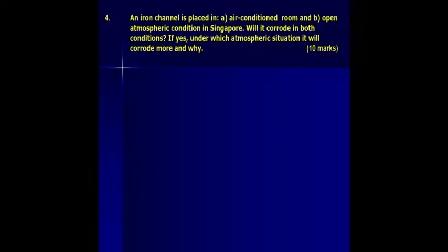So what is the difference? The difference is three differences. First is the category of corrosion is different, and the iron oxide in the wet condition is not a stable or good oxide, it falls off. You have seen brown rust falling off from the iron-based products. Number one, oxide layer is not protective in the wet condition.